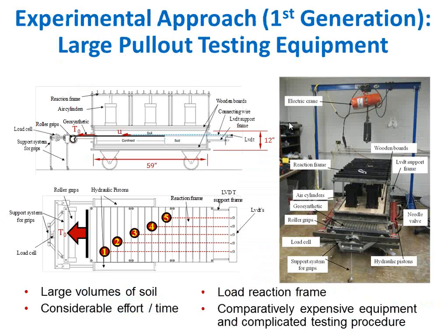This is a big-scale test, at least for what conventional tests are in geosynthetics and in geotechnical engineering. It is a comparatively big box. We apply the loading here, and we monitor the load internally with telltales at different stages, at 5 different locations. And this is what the pullout box looks like.